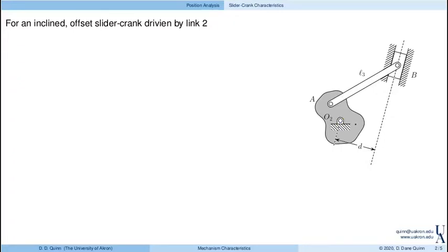And here, link 2 is represented by this strange blob shape. Really, what's important is the constraint that link 2 is pinned at O2, and then the connecting link is pinned at A. So you could think about putting in just a rigid link between O2 and A, and we would have a common, familiar configuration.